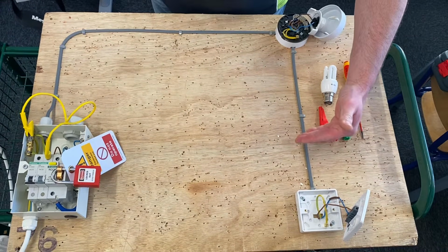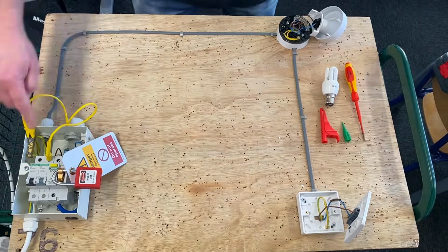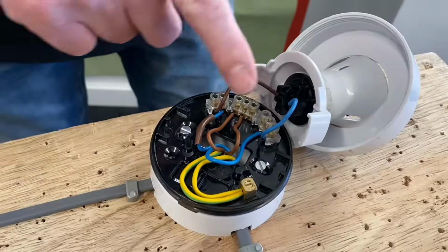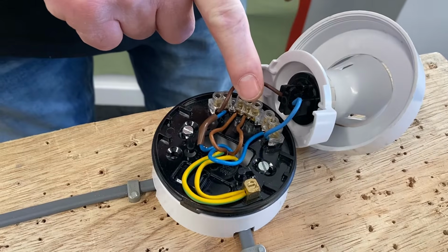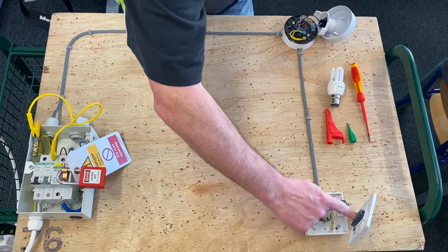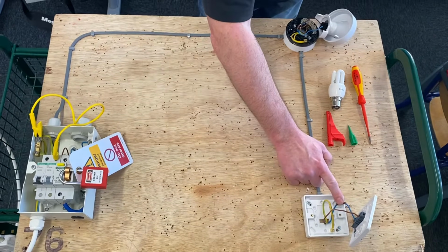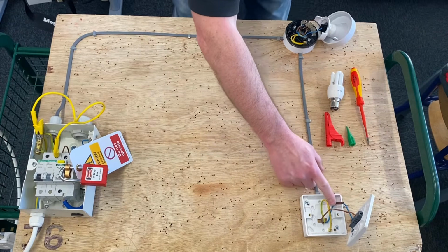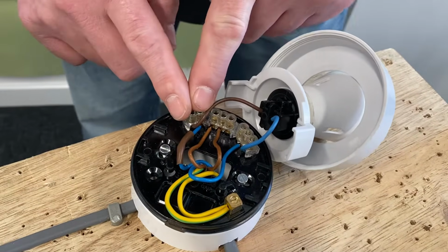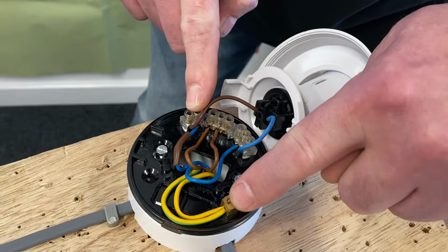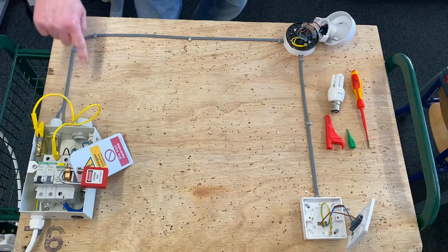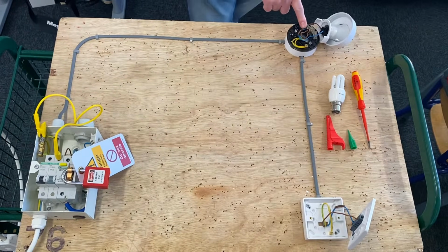Well, let's think about the circuit that we've just measured its resistance for. The line connection here comes from the breaker. It comes into the loop-in terminal in here, and we've looked at that before in the channel. It comes into loop, it goes down to the switch, and then comes back on the blue conductor identified with brown sleeving, which is my switching line, back to here where we measured its resistance when we're at the lighting point. So we measured from the switching line to CPC here with that full length of run in and achieved our reading. So it came line conductor through, down and back for measured point to here.